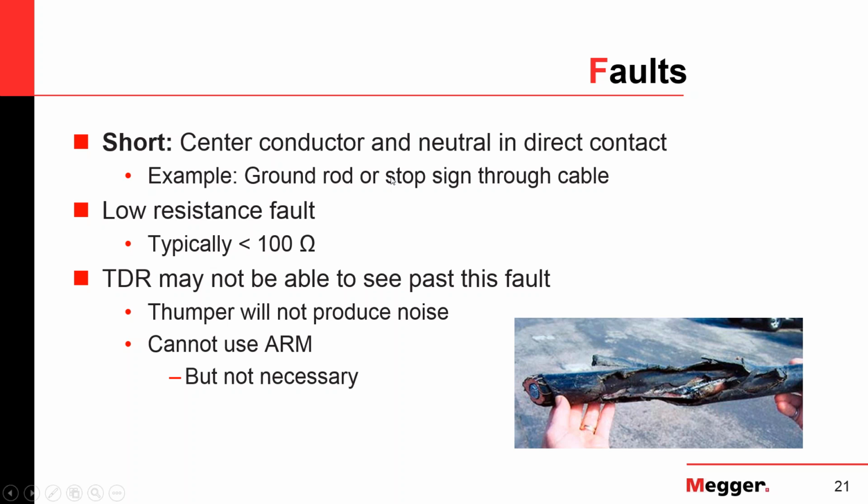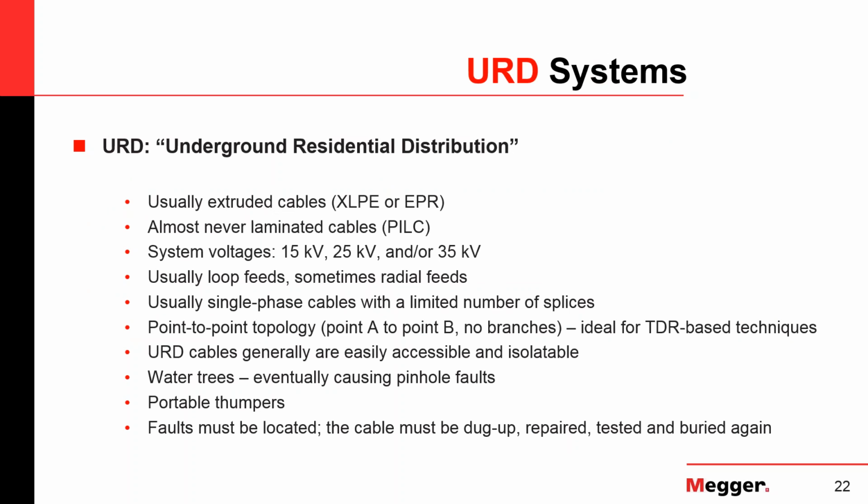The problem also with those faults is, I just want to mention it, since it's a short, you will later see that there's no possibility to create a flash over there, a spark. And so you also cannot really use the arc reflection method on those faults.